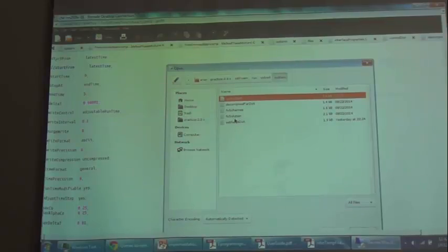Maybe that's why there is an alpha Courant number here. Where's the alpha? So in interFoam you have this. I don't see this in interFoam. This should be there because the interface changes its location and then everything changes, because the diffusivity is also included. The diffusivity is a function of which phase it is in, right? Do you know how this alpha Courant number works? It should be there in theory. We can test it probably.